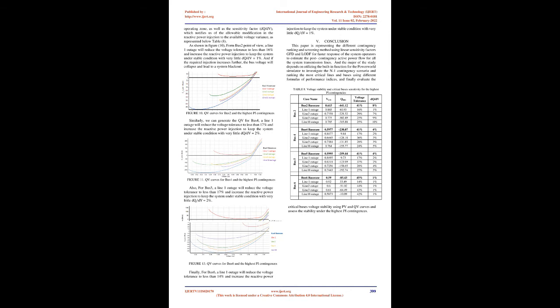But considering the bus voltages for the remaining buses and calculating the voltage performance index in Table 6, it's observed that the most severe outage occurred when the bus 6 substation got out of service with PI_QV equals 2.84 due to 2 buses going under voltage limits, then bus 5 with PI_QV equals 2.60 due to 4 buses going under voltage limits.